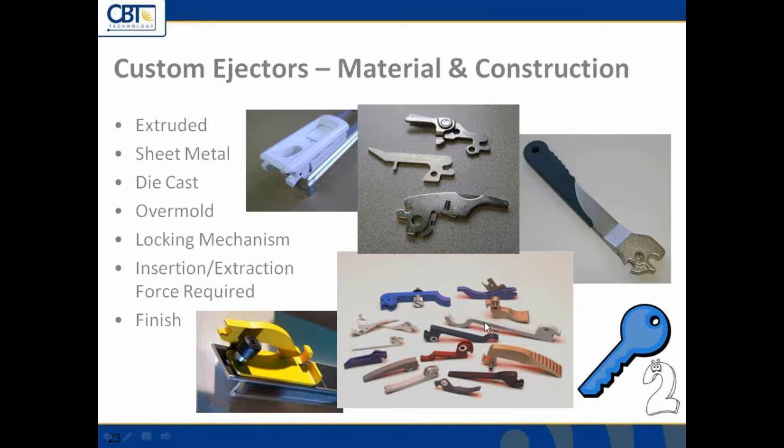You have certain ejectors that are very long. So the amount of leverage required to extract that board from the chassis, because of the actual pound force that they have was so high, they had to have a nice long lever to be able to accomplish that goal. And then you can see it varies. And there are some others that are much smaller because there's not as much force required. So all of those things are options. This particular customer back here in this blue version actually had a little bit of a gear mechanism that was used to pull it out in stages. So a lot of different options there as far as those ejectors are concerned.